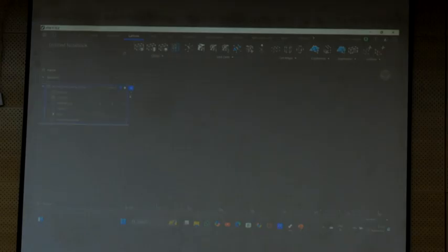So the rectangular coordinate system. Once I press rectangular lattice, it asks for some optional inputs, you can just leave those, but the empty required ones we need to fill. See, volume, it is asking what is the volume, the original design, okay. That should be an implicit body, not a CAD body, it won't take a CAD body. That icon is the implicit body symbol, okay.